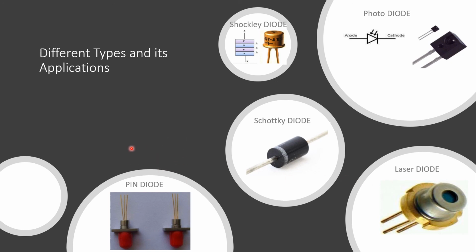For the last example of different types of diode, the PIN diode, it consists of heavily doped P and N regions separated by an intrinsic region. When reverse biased, the PIN diode acts like a nearly constant capacitance, while when forward biased, it acts like a current-controlled variable resistance. The low forward resistance of the intrinsic region decreases with increasing current.